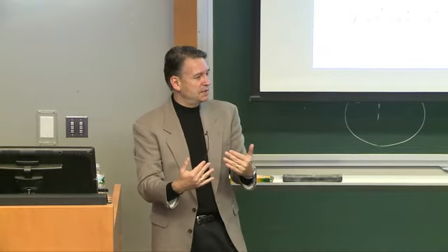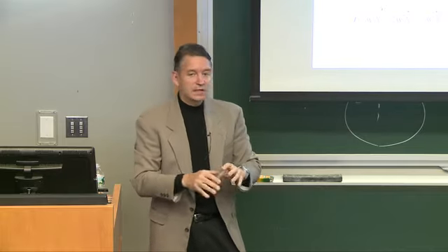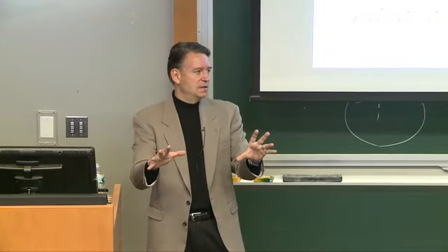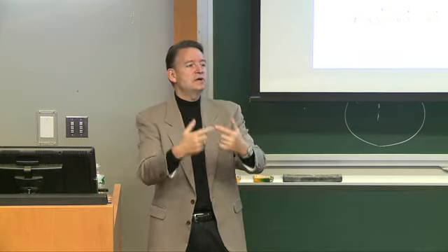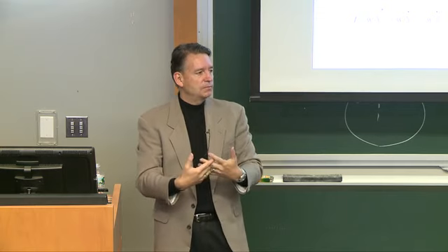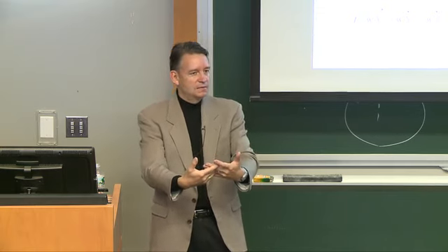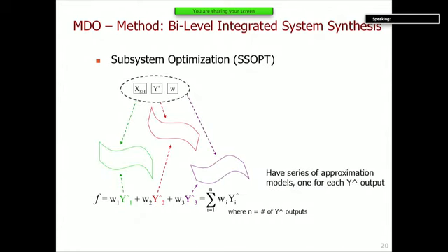And you can store that information and then use what are known as approximation methods like response surface models to save that information, such that when you do the full system optimization, you don't have to rerun the detailed codes every time. You can just pull from the approximation you've pre-computed already. So that's one of the really powerful things about this method.